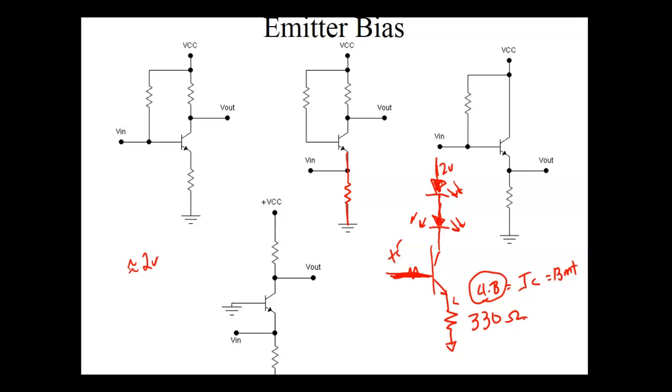So those are LEDs. What would happen? 13 milliamps, until I run out of volts, right? We were dropping about 2 volts, and this guy right here is dropping 4.3. So when I got up to about 4 LEDs, I put another one in there and it didn't work anymore, because I didn't have any more voltage up there. Technically I could put 50 volts up there and keep stacking those LEDs, and it doesn't make any difference until they drop more voltage than supplied.